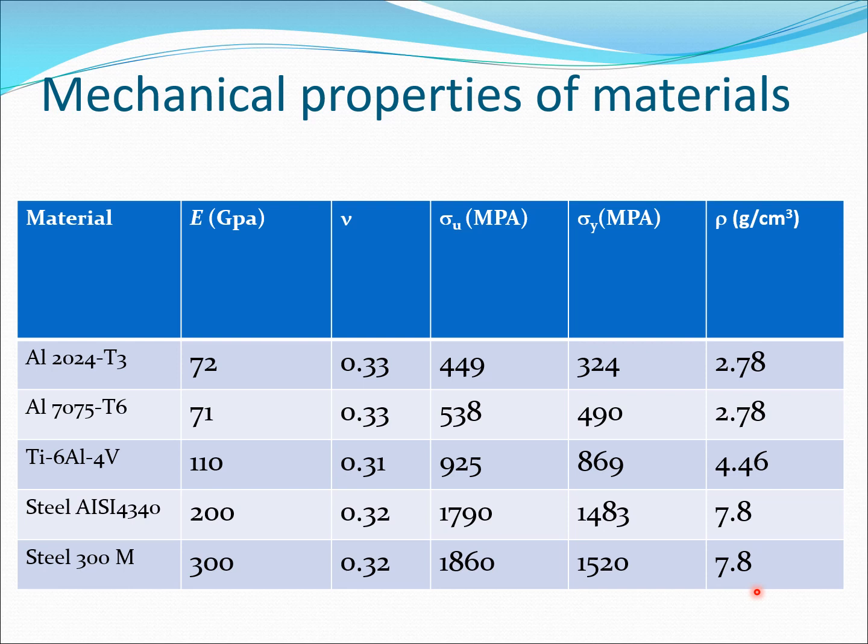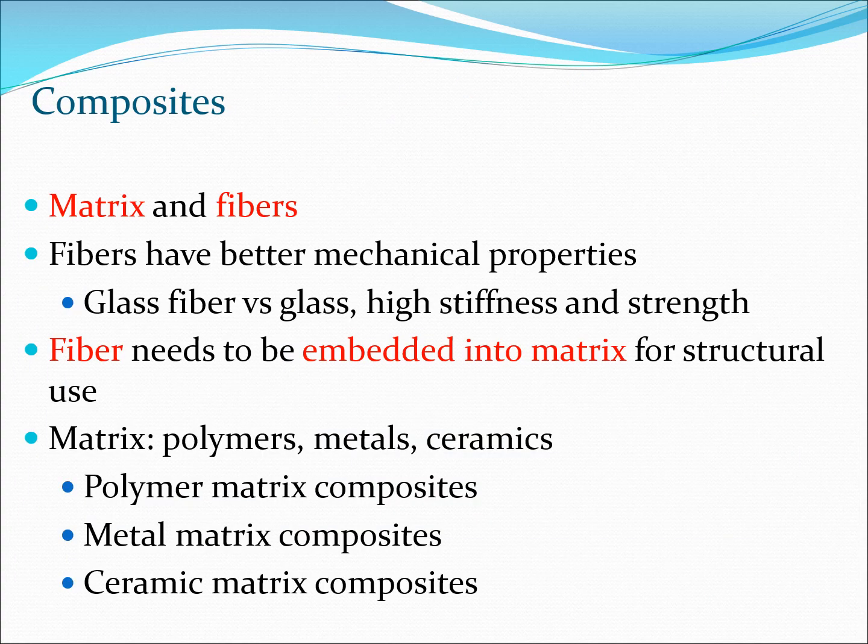So generally what is done is that the aluminum wins out because of its superior stiffness to weight ratio. So the two things going here is that we want stiffness, but we also want low weight. So this is a particular characteristic which drives the aerospace vehicle material selection. We are not only concerned with the material having a high stiffness value, we are also concerned with the weight side of the equation. So that's something to keep in mind.